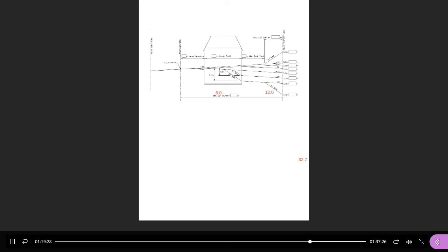Sorry, this is wrong too. Let's type this. This should be 389, not 3.39. Negative 3.89 at the bottom. Sorry. So again, if you calculate, start at 0, go up at 2% for 8 meters, go vertically to the back by 1.2, and then go all the way to the back at 3%. You should be 1.42 below the front, negative 1.42.